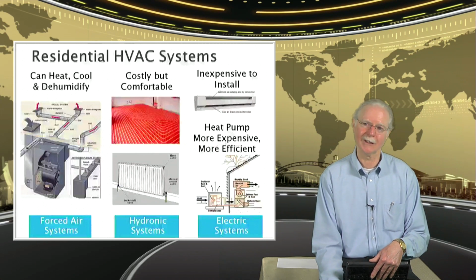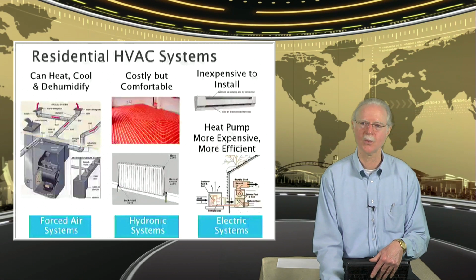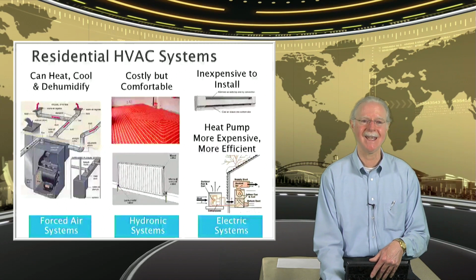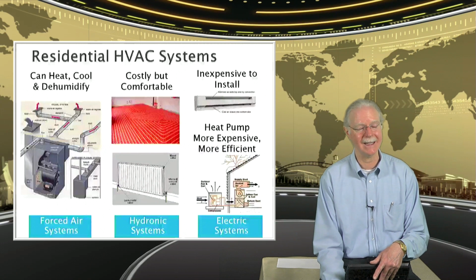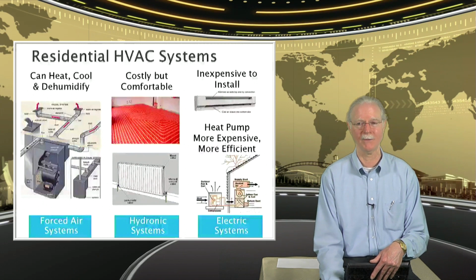So your lowest outside temperature occurs when? Right in the morning, just before the sun comes up. So if you're asking the heat pump to pull heat out of the air at the point when the temperature is the coldest on the outside, then you may not get quite the savings that you were hoping for.